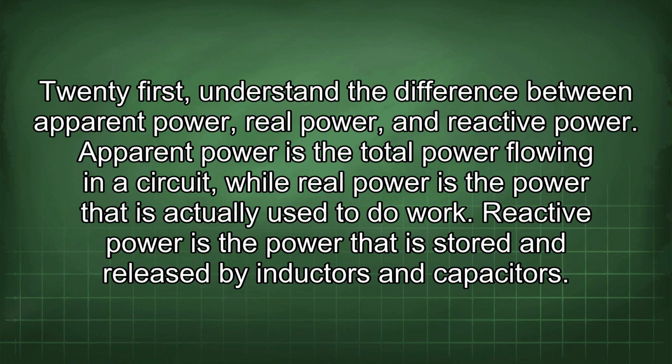21st, understand the difference between apparent power, real power, and reactive power. Apparent power is the total power flowing in a circuit, while real power is the power that is actually used to do work. Reactive power is the power that is stored and released by inductors and capacitors.